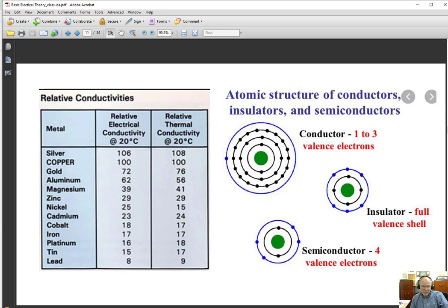One is the aluminum wiring in houses, where it was connected to a device with a screw that was made out of a different metal, would tend to corrode to the point where it would then lose its good contact, and that contact would become loose, and the loose contact would cause arcing, and the arcing would burn down the houses, which is why you don't find any houses now with aluminum wiring. They either burned down or somebody went, oh my God, I'm getting rid of that aluminum wiring because my friends' houses are all burning down.